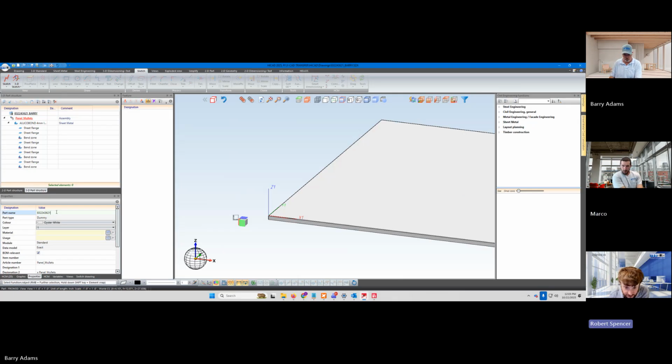However, on your HiCAD side, you're never going to see that number because you gave it an article number in the catalog that will come up in your menu. So you could make that better if you want. I would recommend doing it at the beginning rather than now. Or you could leave it alone because you get a nice article number in the catalog entry. It's kind of up to you.